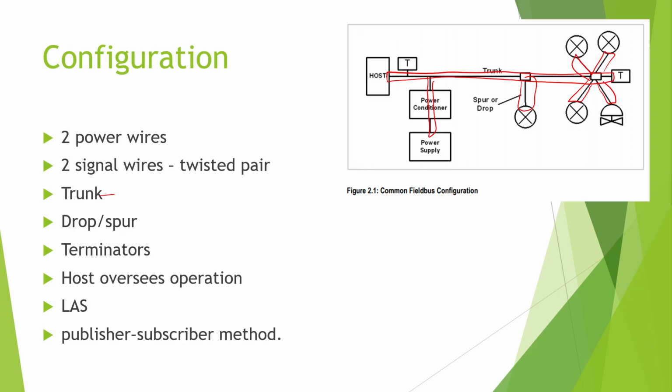And what that terminating resistor does is it basically makes the wire feel like, according to the electrical signals, it's infinitely long. So the signals hit that terminating resistor and they kind of technically burn up. I mean, they become heat. They're burning up. So that's what's happening with those terminating resistors or those terminators.